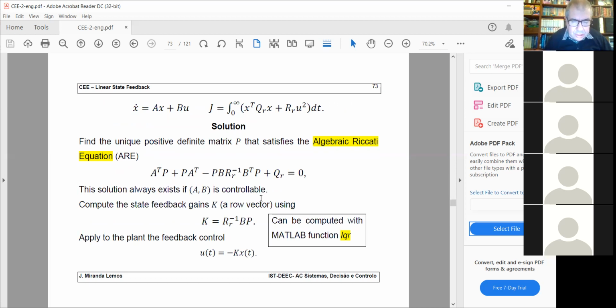We are going later to see the solution. Actually, proving these formulas will be part of the last part of the course, but let me give you right away the solution. So the solution is a state feedback. Look at the bottom of the slide. So the solution is minus some gain Kx. So it's a state feedback, exactly as what we have been studying. And this K is computed according to this formula.